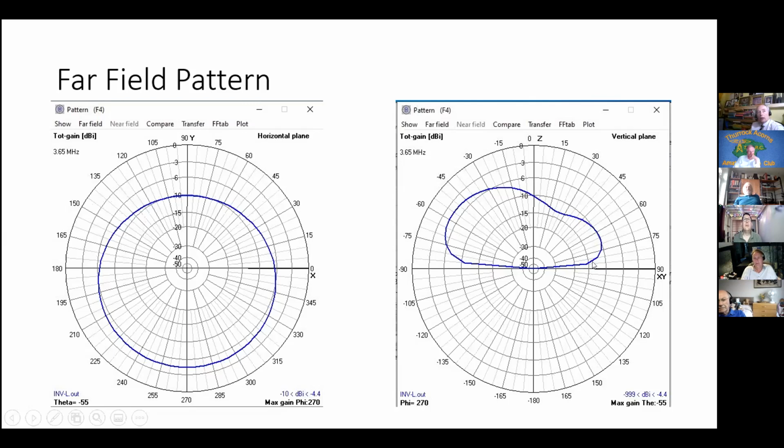What is interesting is that although most of the antenna is horizontal, most of the actual radiation comes from the short vertical piece. And what you find is that it has gain of, if we remember that we were about -8 at low angles, here we're -6 down to about 15 degrees and about -10, almost flat to the ground. So these things have much better low angle gain, but much less high angle gain and very little off the top. So they behave very differently to a dipole.